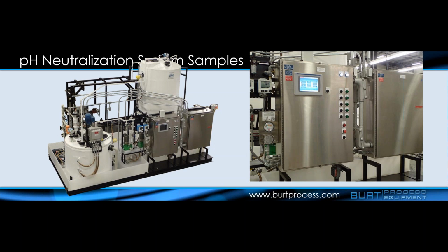Have you ever had cases where the addition of the reagent releases so much energy that a heat exchanger or upgrade in material construction is required? Yes, is the short answer. Generally speaking, acid and base reactions are very exothermic. You generally just don't see it in a standard wastewater treatment system because your waste stream is not very strong. pH 2 waste or even pH 13.5 waste generally has a fairly marginal amount of actual chemistry by volume, or molarity, to cause any kind of significant temperature rise.